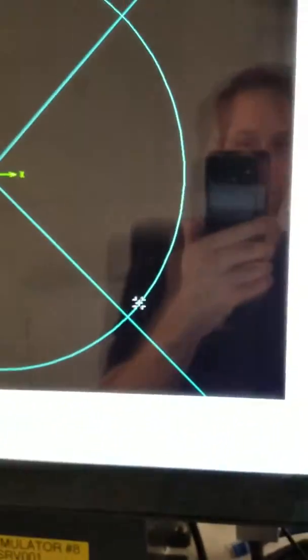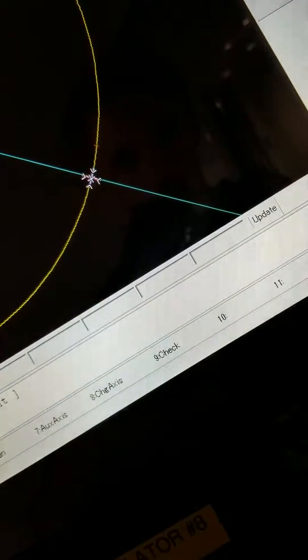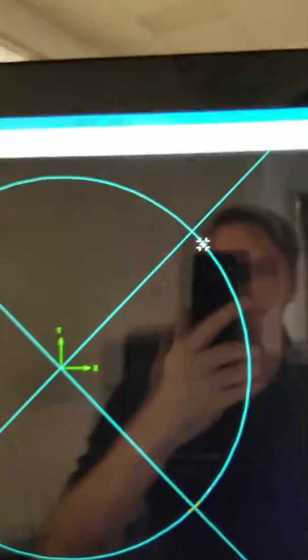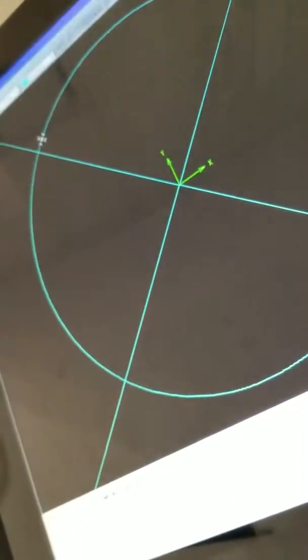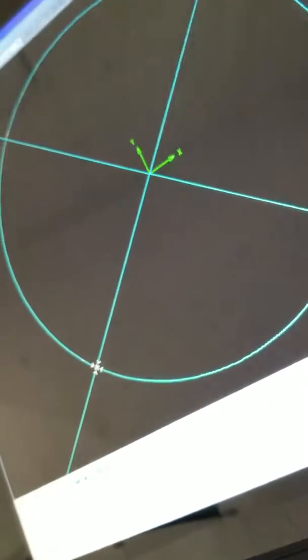So you're going to click on your circle, and then you want to tell it now the break position. So what you're going to have to do is hold down Shift until you get the snap tool active, and then click the intersection. I just broke that circle into that segment. So you have to do this in all 4 quadrants. You know, there's our line, there's my break element, there's my line, there's my break element.